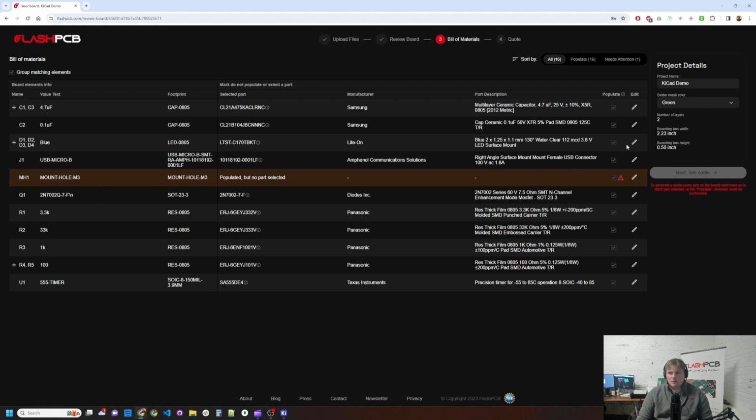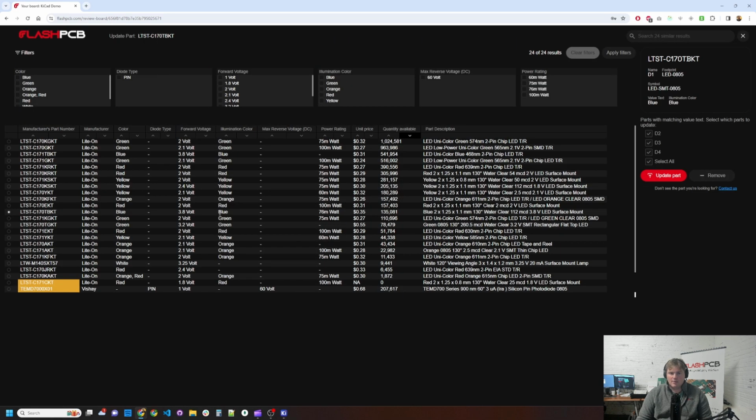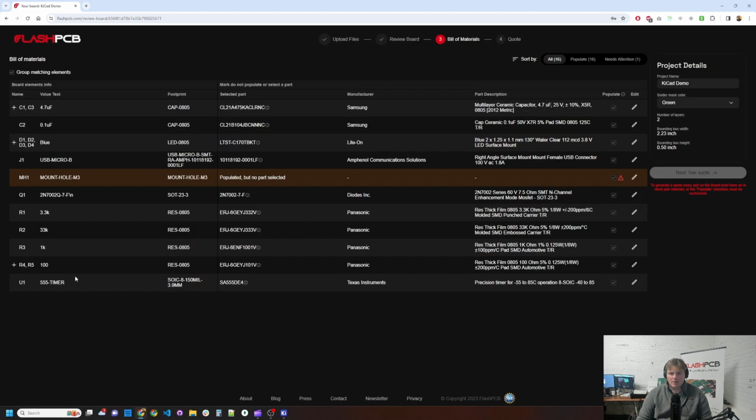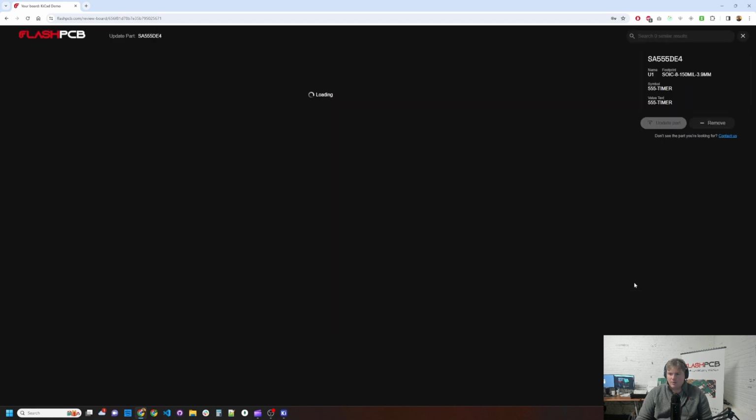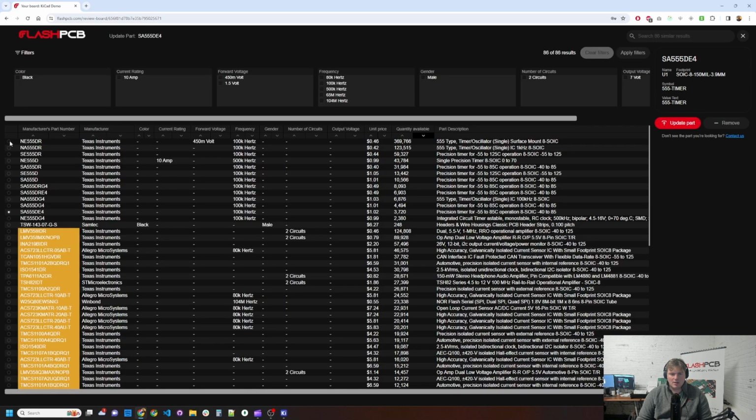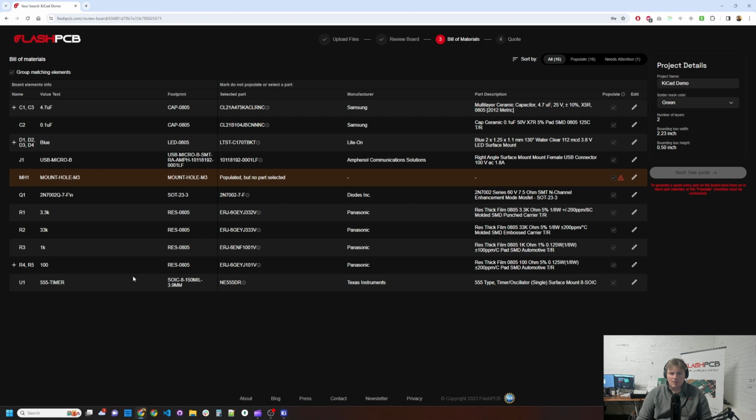If you'd like to change anything, so for instance, you want to change your LED color, we can come in here. Maybe we want green, maybe we want red. This is all available for you to change. I'm going to leave this one as blue, but let's come and have a little look at this 555 timer. So for instance, this is a Texas Instruments one, and it's an SA555. I think I want an NE. So we'll come in here and we'll say, yep. So this has much higher quantity available. I think this is going to be a little more of a common component. So I'll go ahead and select that. I'll hit Update Part, and that's now filled in on our BOM.